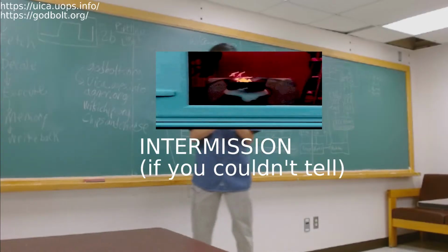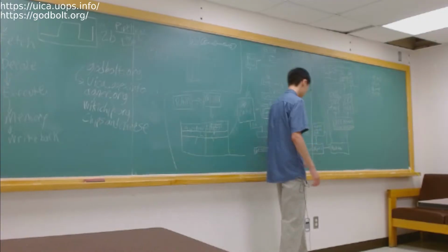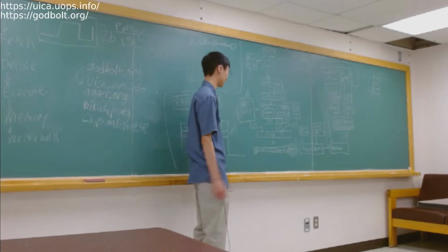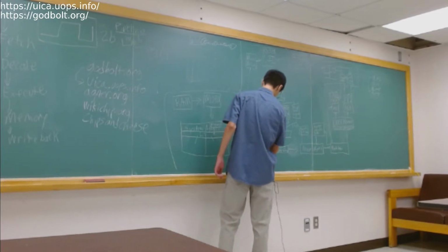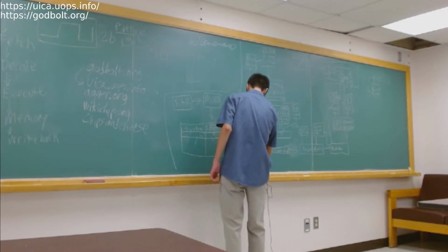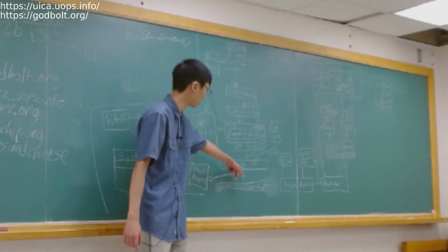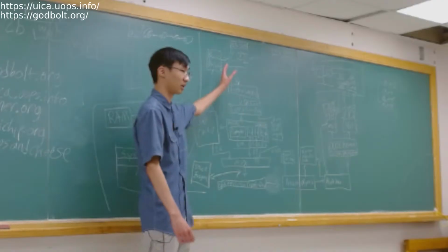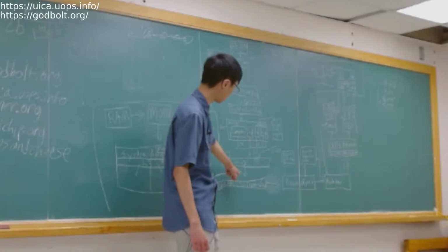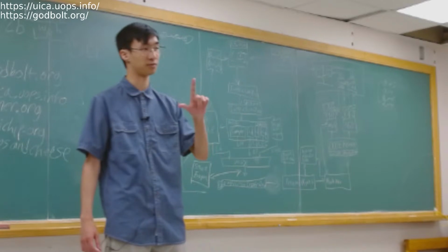Okay, let's talk about this. I missed a couple things by accident, just some minor things that I always forget exist because I don't really care, and then when I find out, I'm like, oh, right. So there's one thing here called the stack engine. The stack engine's job is to check the output of the decode set, this legacy path. This is called the cache path. The legacy path is over here. With the output of this, we're trying to find out, do we have a push? Do we have a pop? Those two instructions modify the stack pointer.